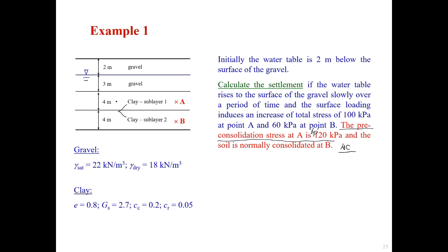And also for this type of settlement, we again need to calculate at the middle point of each sublayer, and the settlement of the middle point represents the average settlement of that sublayer.